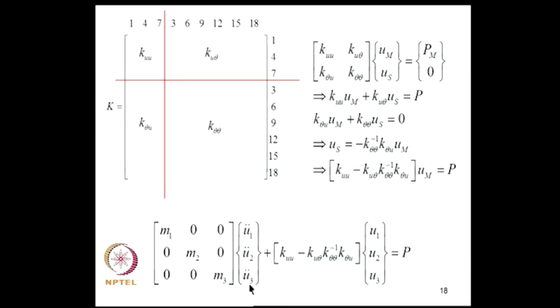These are the 3 horizontal accelerations. This is the equivalent stiffness matrix, which takes into account joint rotations. So, I get this as a 3 by 3 matrix. In the traditional shear building model where joint rotations are ignored, this correction would be absent. So, we get this equation. That can be further analyzed to get the properties of the structure.